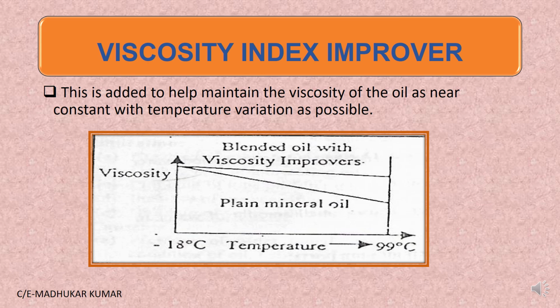So now we will go one by one through the different types of additives. Viscosity index improver. As we know, when we talk about the viscosity index, it basically helps to maintain the viscosity of oil as near constant with the temperature values.